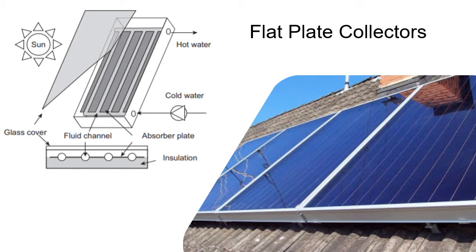These absorber plates are usually made out of a metal that is a good conductor. They are painted with special coatings to increase absorption and the retention of heat. The sides and bottom of the collectors are also lined with a layer of insulation to reduce heat losses.